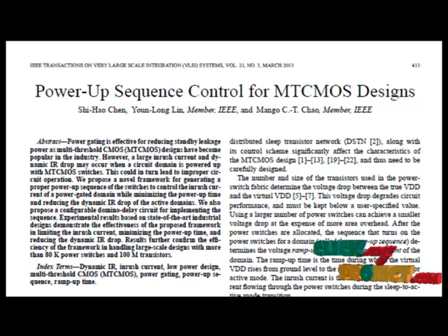Asynchronous designs offer these advantages inherently as they are data-driven and are only active while performing useful work. In other words, asynchronous circuits implement the equivalent of a fine-grained clock gating network. However, while dynamic power loss has been the dominant culprit in the past, static power loss has become a considerable contributor to power consumption in nanotechnology.